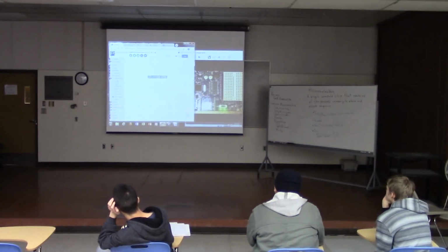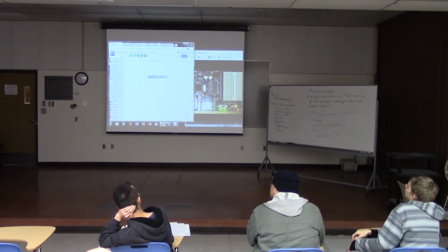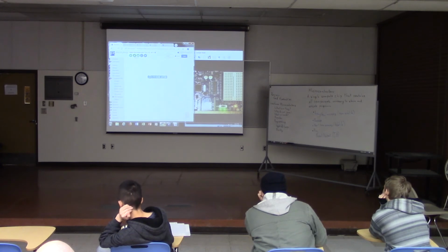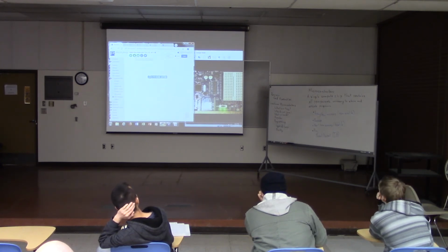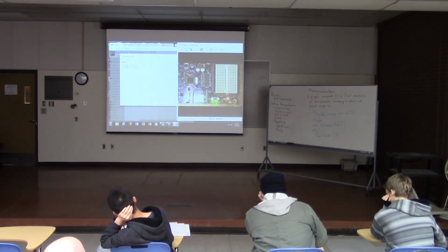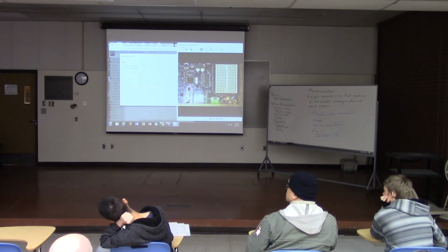It's just got a single command, but it should still do something worthwhile. So let's try this out and see if it works for us. I'm going to click this little run arrow here, this little down arrow, and that should run the program on my controller. So let's see if that goes. It said it succeeded, and now if I look at my microcontroller, I can see that that light is just turned on. So I set pin 26 to be high, that turns the light on. Okay? So our first program worked, right? Just a single command was able to do something interesting.